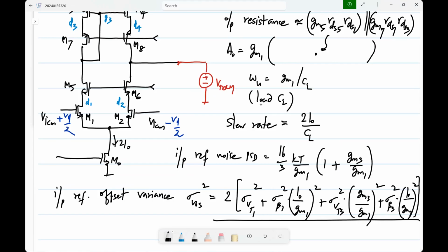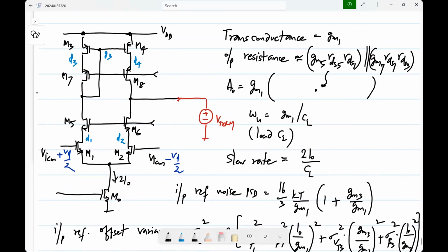Extra poles. Now, if you think of only I out by Vd, not V out by Vd, how many parasitic poles did we have? 1. That is because of the gate of M3. In fact, that created a 0 pole, right? You get half the current at high frequencies and so on.